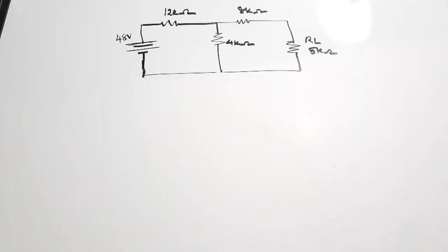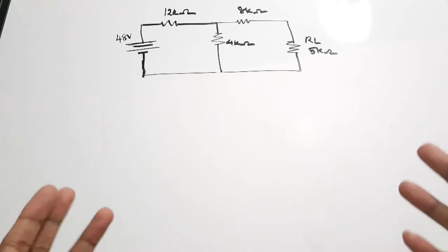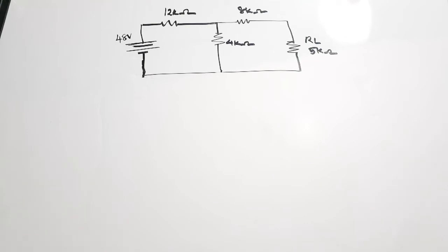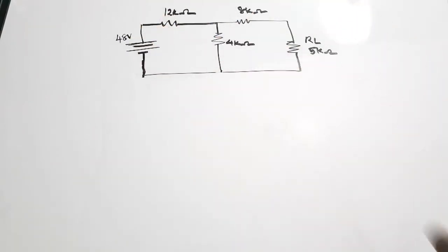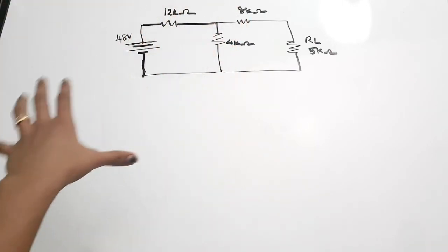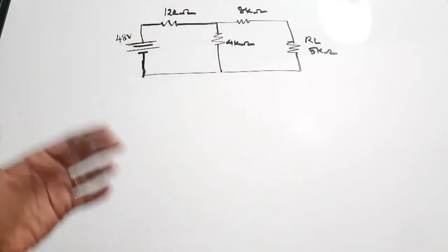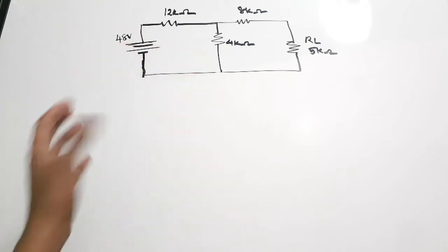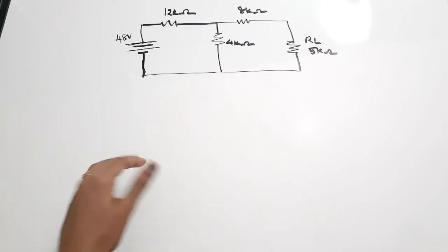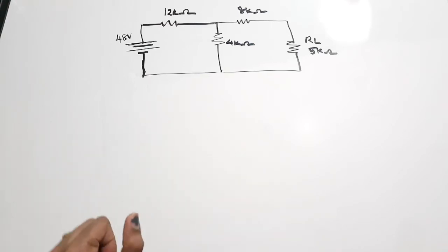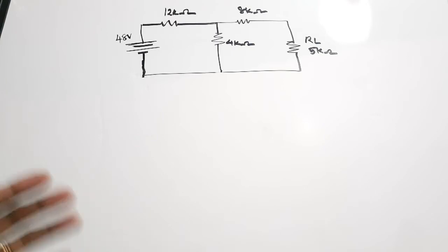Whenever we have a circuit and we use a load, our aim is to find the total voltage or the total current in the circuit, right? So in Thevenin's theorem, we are going to keep the load as it is, and take the remaining portion of the circuit, however many voltage sources or resistances there may be. We are going to simplify the entire remaining circuit as a voltage source and a series resistance. That is, we will be doing a simplification.